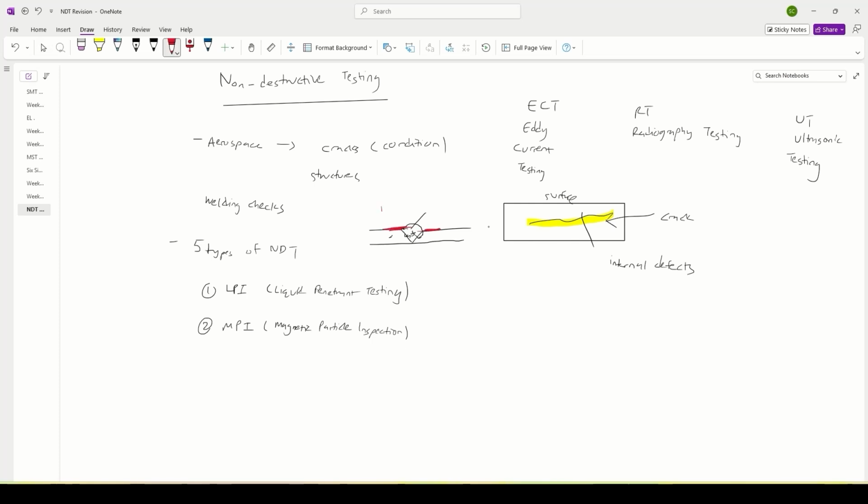First step is the penetrant. Second is to wipe it off. So you remove the penetrant and you apply another coating, which I will call blue this time, and this one is the developer, to develop the cracks that the penetrant has penetrated into.